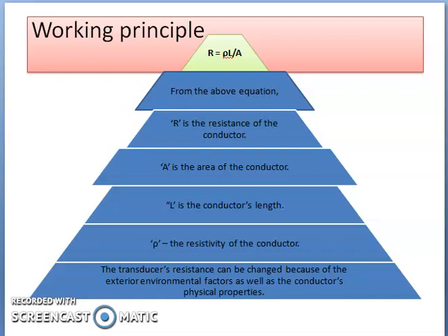That is, resistance is directly proportional to the length of the conductor, and inversely proportional to the area of the conductor, and it also depends on the type of the material, that is rho. This is the basic working principle of resistive transducer, and the resistance can be changed because of the external environmental factors as well as the conductor's physical properties.